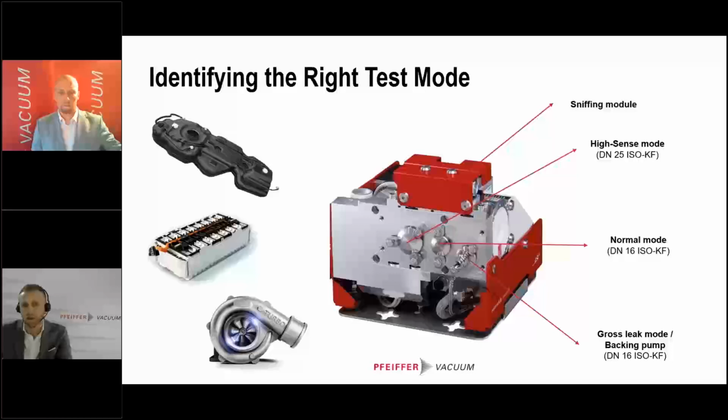Okay, so in the beginning, you first need to select the right product for your leak test system. Usually with a high throughput in the automotive market, we are talking about a modular leak detector, which can be integrated into a system and which communicates with an external interface or an external PLC. In our case, this is the ASI 35. This is our modular leak detector.